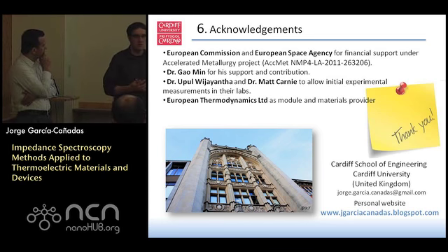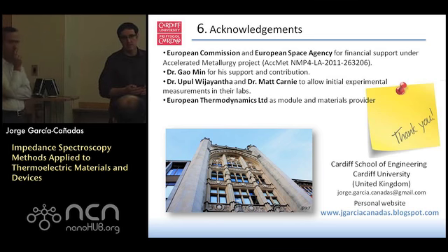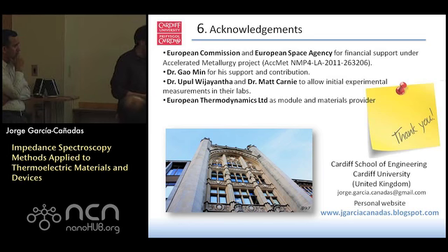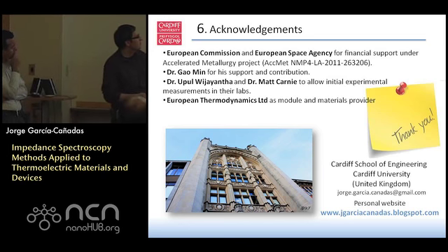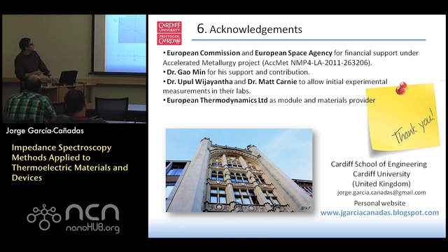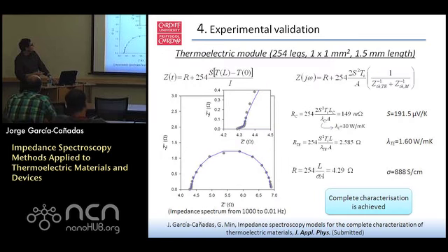When you go to lower performance materials, your resistance becomes smaller. So now we are working in the milliohm range, and this is difficult to measure in some equipment. But you can gain accuracy by changing the geometric properties. For example, if you increase the length of your material, your resistance will become larger.